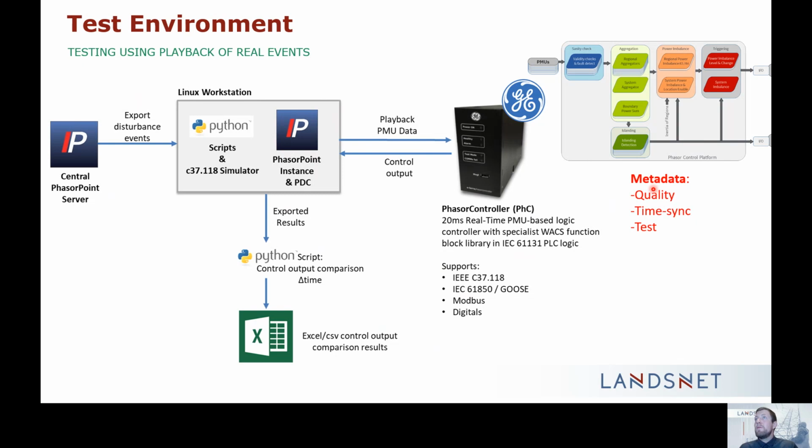Again, similar to 61850, we have metadata assigned to each of the signals flowing through the whole system all the way to the IOs as well. So it carries the quality, the time sync, the test flag, everything. So we get full control of the metadata to decide when to use the signal and when not to, when to trigger the IOs, implement the test flag, and so on.